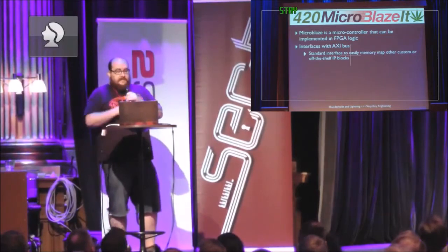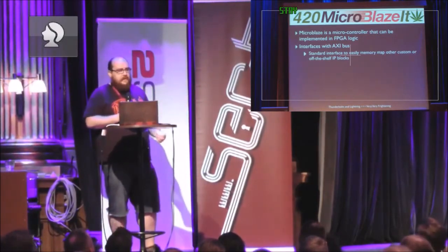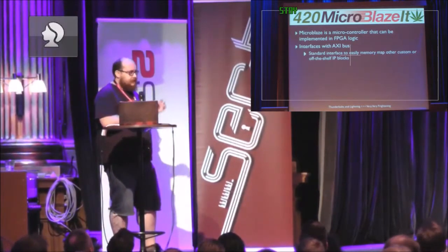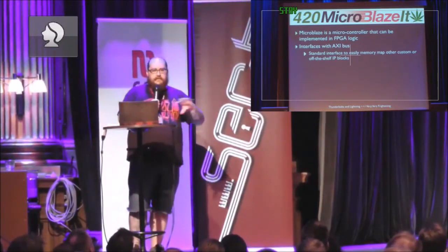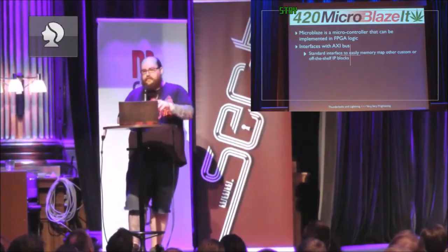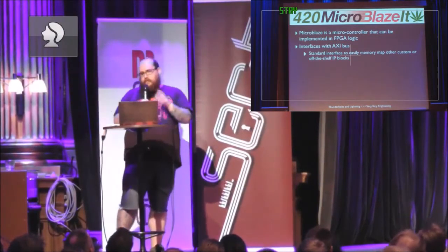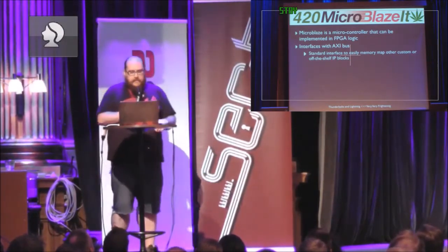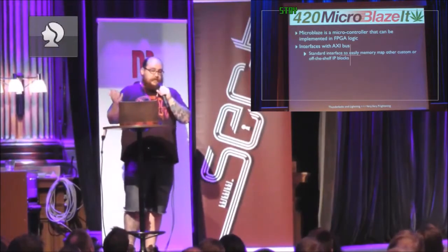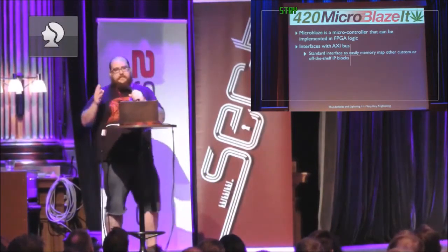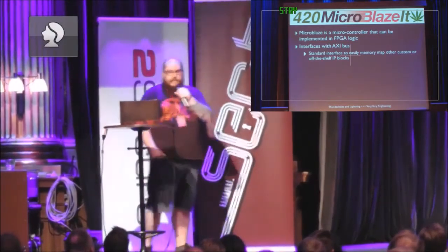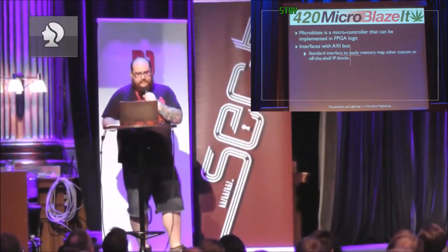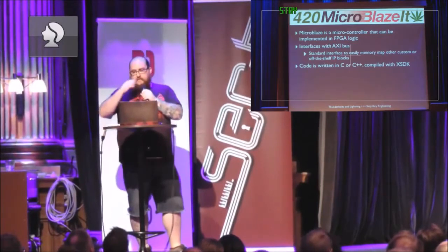Yeah, so AXI is very convenient for us in this case because there are lots of off-the-shelf IP cores, which are just chunks of FPGA logic that other people have already developed that you can license or borrow. Lots of them talk AXI, lots of them talk Wishbone and various other interconnect formats, but AXI is quite convenient because all the Xilinx stuff pretty much talks AXI. So MicroBlaze, like this,